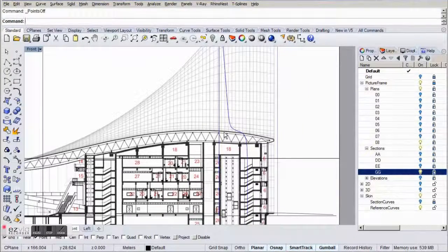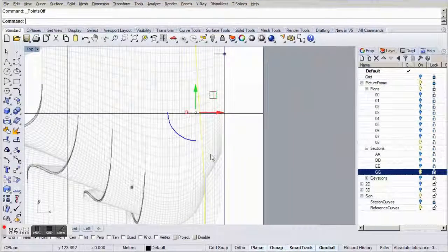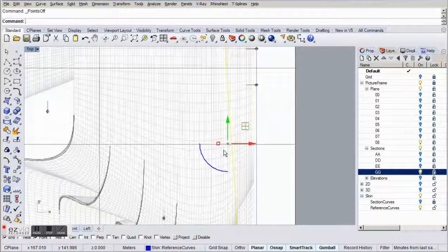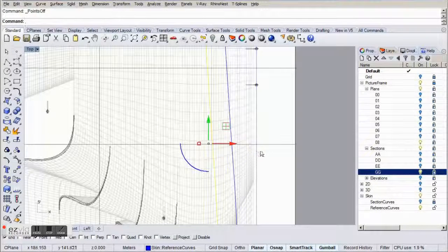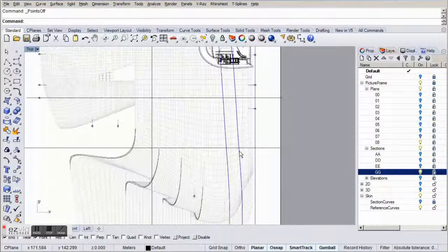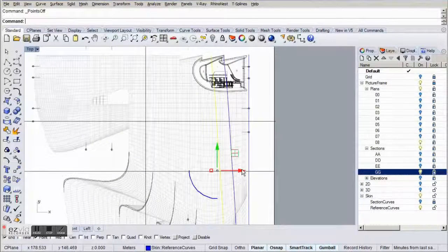Let's continue with the next reference curve, and for this one we can simply copy the one we just made over to the left side. Again, if you want to copy an object, simply hold Alt and press the control handle and specify an amount. For instance, let's use -10. And you see the line got nicely copied over. Now let's position it again where the facade splits open.